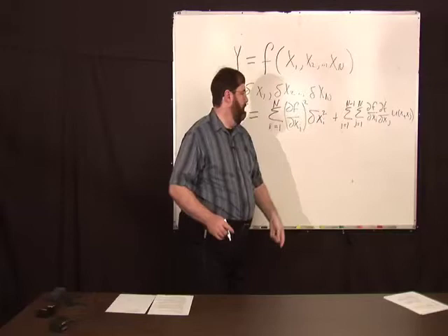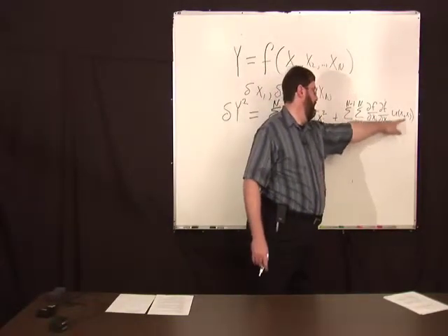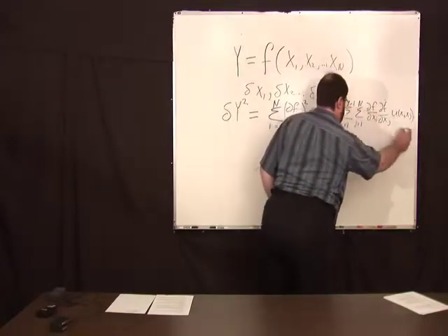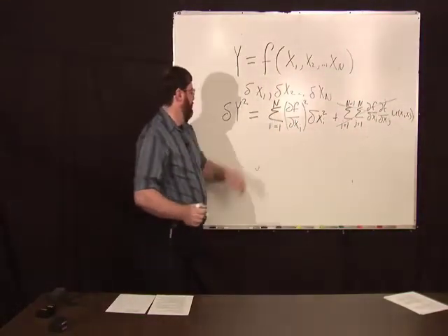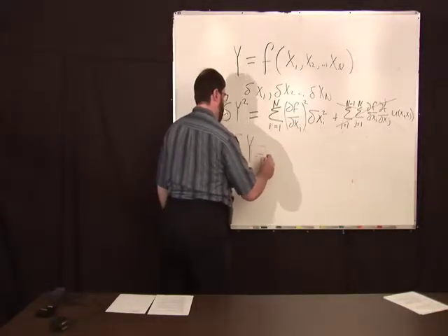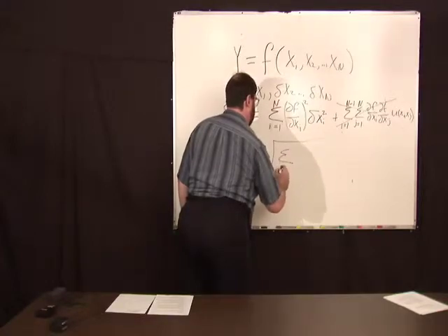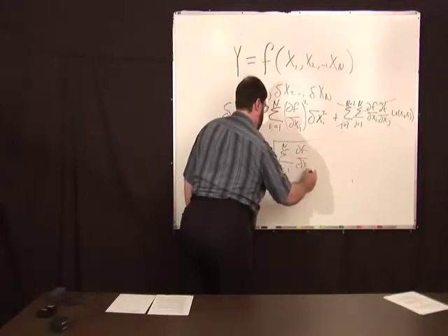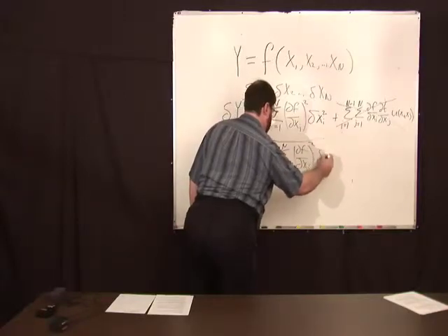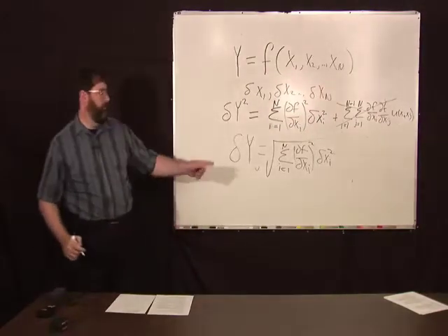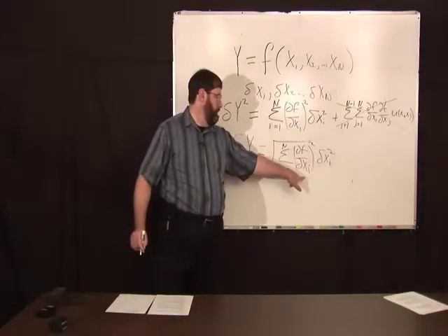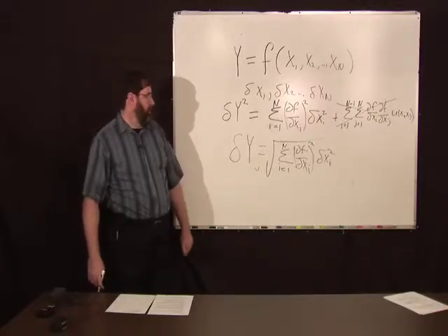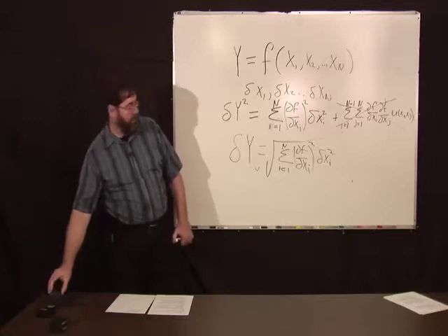This second term, this last part here, is the covariance between two variables, xi and xj, and the two partial derivatives. We're not going to deal with that here just because of time, but maybe at a later time we can go into how you deal with that. So a good estimate then for the uncertainty, that's the RSS uncertainty, is just the sum of all the derivative with respect to each variable times its uncertainty squared, summed up, the RSS. I'll give some examples next to make it easier to understand how this works.